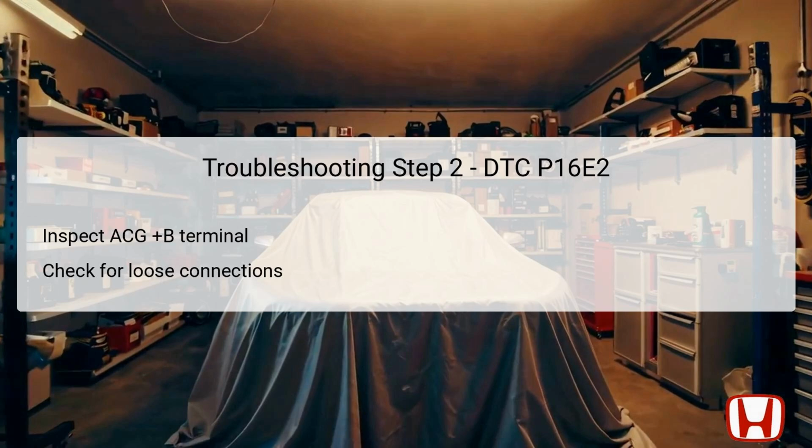Efficient identification of this issue could save significant time and effort in unnecessary repairs. The third step focuses on inspecting the alternator's functionality. This includes performing specific circuit tests to ensure that the alternator is generating the necessary output and that it's functioning within its normal operational parameters. Utilizing a multimeter or specialized diagnostic tool will allow you to measure voltage output and inspect for correct indications.